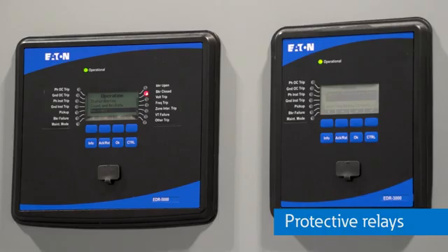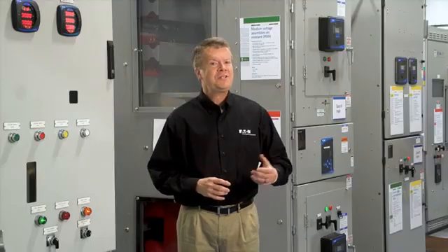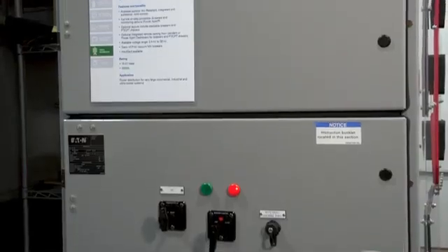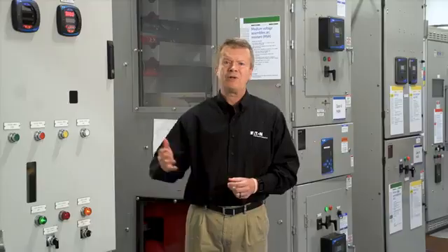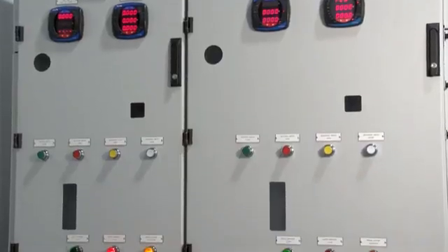For medium voltage, protective relays are used. In many medium voltage applications, multiple protective relays or a multifunction relay is required for overcurrent protection. Relays also offer many other protective modes like undervoltage, overvoltage, synchronization, and arc flash protection. Our VCPW medium voltage vacuum breaker would go into this standard or arc resistant switchgear, and our XGIS breakers would go into this gas insulated 38 kV switchgear.